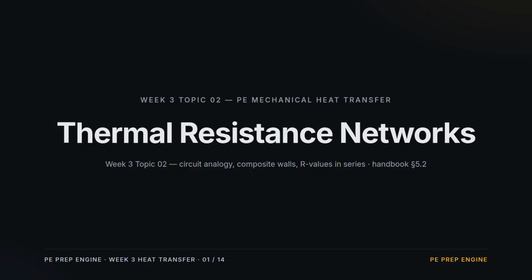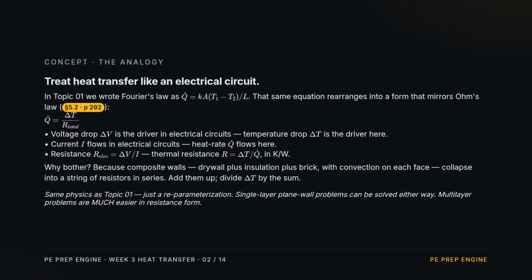Topic 2 of Week 3, Thermal Resistance Networks. We rewrite Fourier's law as a circuit, stack resistances for composite walls, and walk a worked problem with two convection boundaries. Treat heat transfer like an electrical circuit.